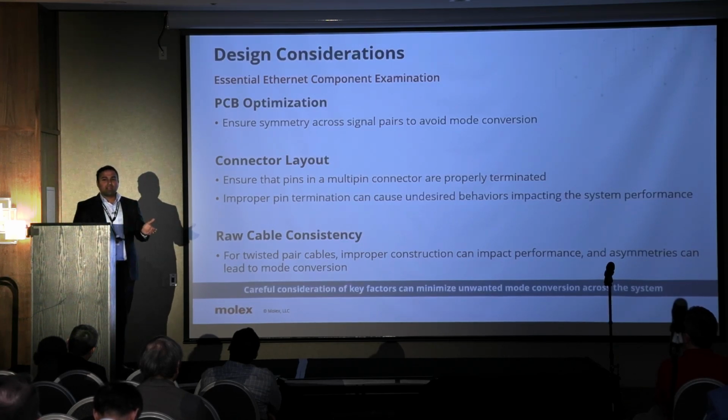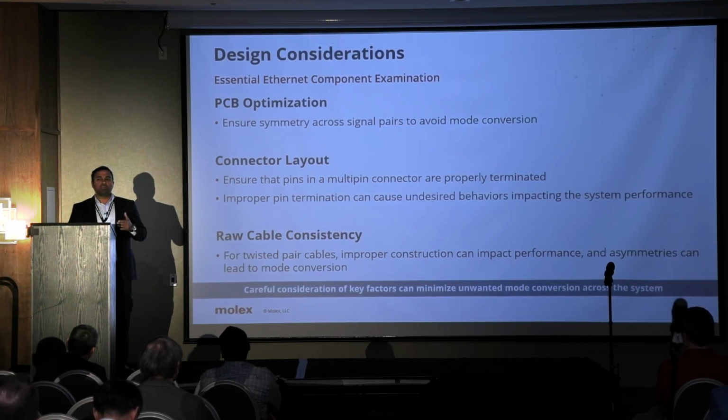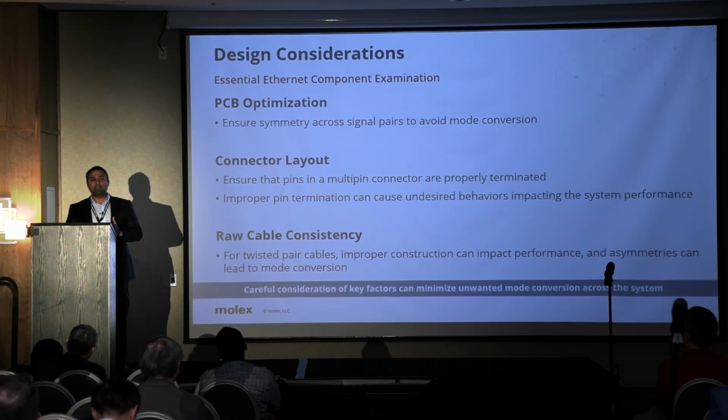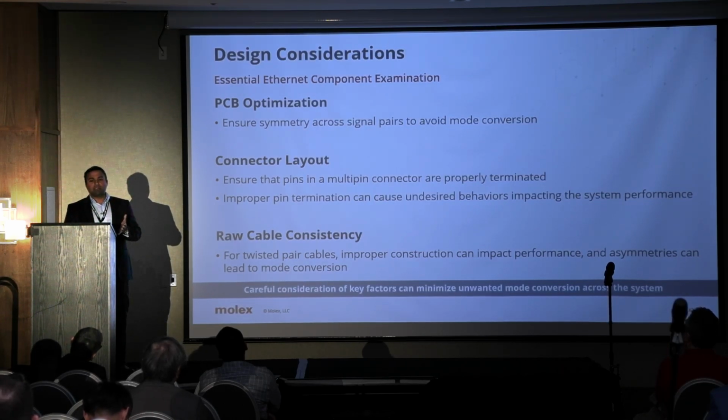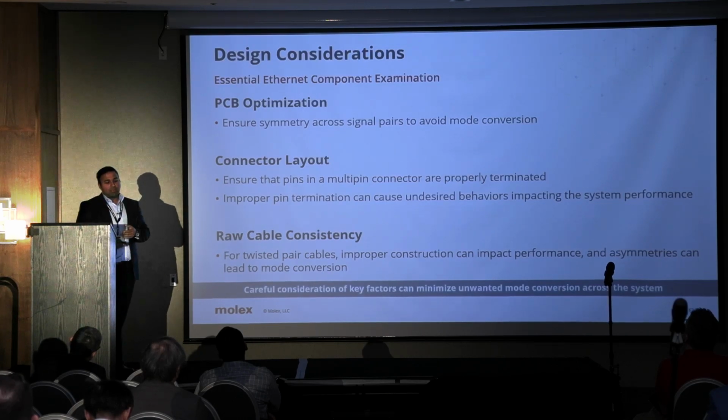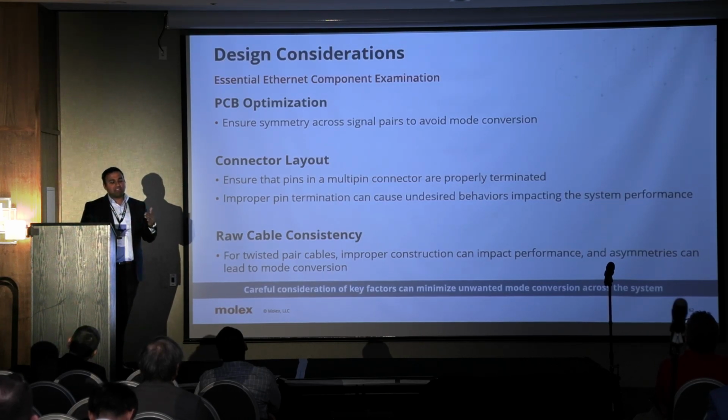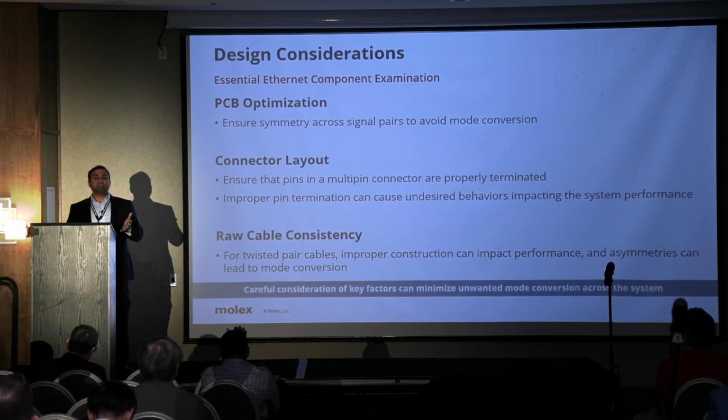And the same thing in the connector pin layout, right? Making sure that all your pins are properly terminated. You don't want any unterminated or improperly terminated pins that can act as another component that leads to imbalance, creating mode conversions. Improper terminations, like I said, can cause unpredictable behavior that can resonate at any frequencies.